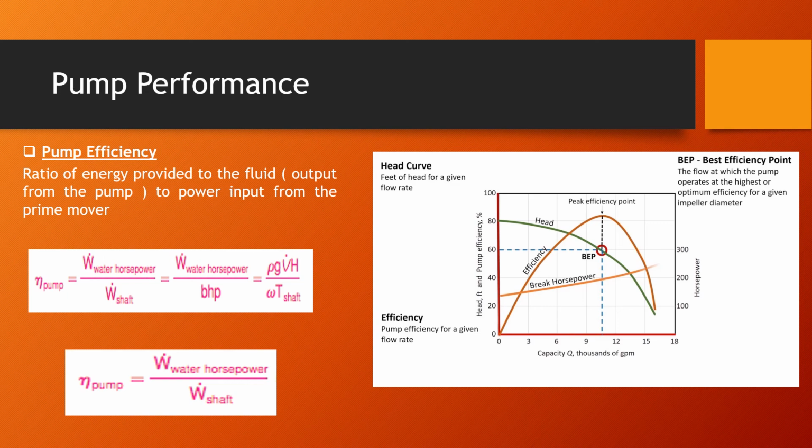That is because as you start to discharge more and more water, the capacity of the pump to take that amount of water to a certain height starts decreasing. So suppose at 3 GPM, if the pump could take it to 80 feet high, at 6 GPM it would be able to just take it to 70 feet high. So it starts decreasing.